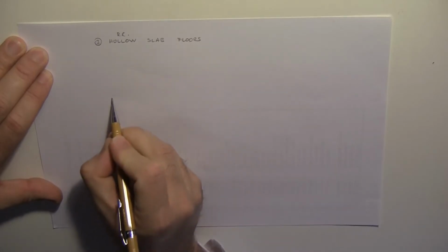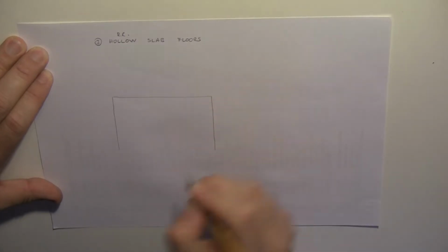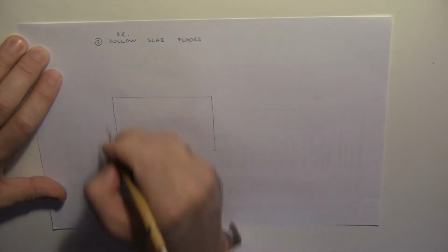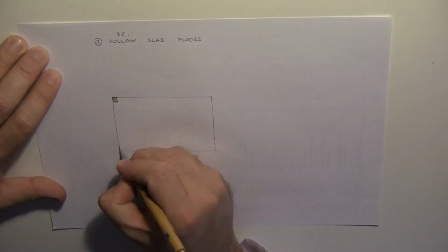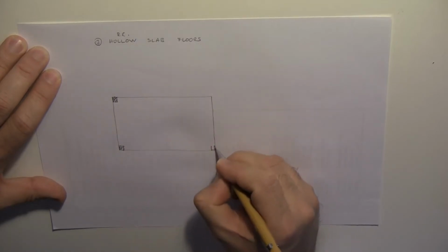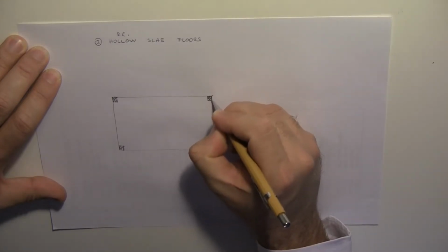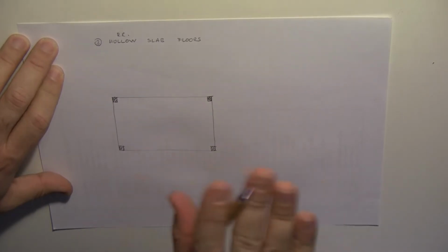Okay? And also, as now the thickness of the floor comes to something around 35 centimeters, maybe up to 40 centimeters, what we need to do is decrease the total thickness of the floor. That's why we are not going to use the beam vertically, we are going to use the beam horizontally.